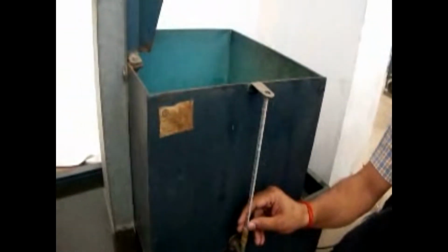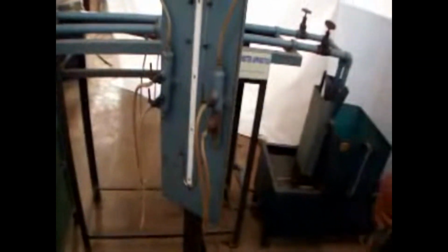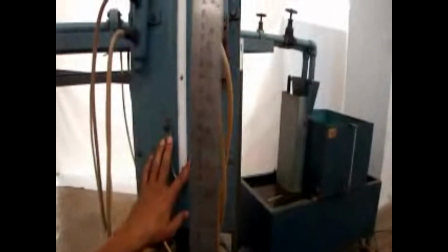Okay, so let us measure the size of this tank which is collecting the discharge. This has a size of 40 centimeter length, and 40 centimeter width as well, and you can measure the discharge in terms of head, that is increasing per unit time, by seeing this scale, that is a stilling basin arrangement. So this is the discharge measurement, and now you can measure the head difference by using the U-tube manometer.